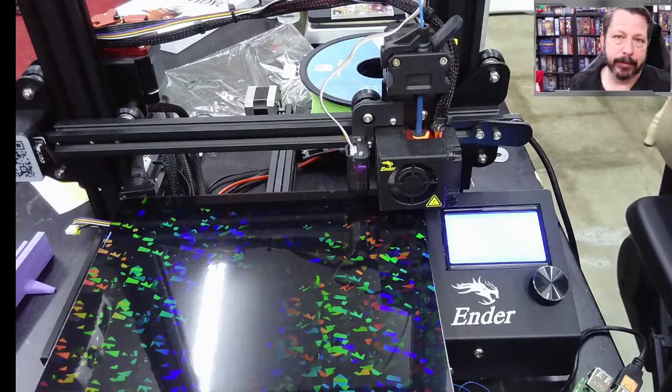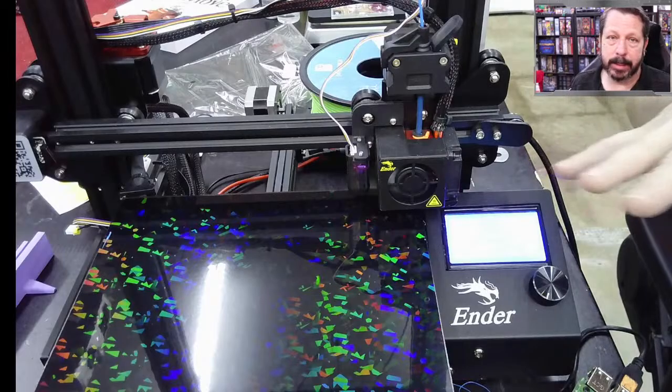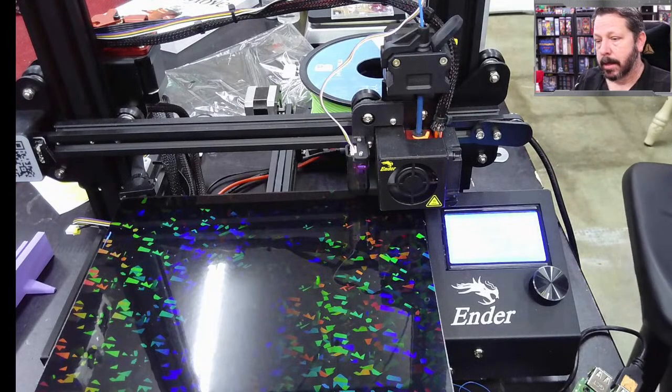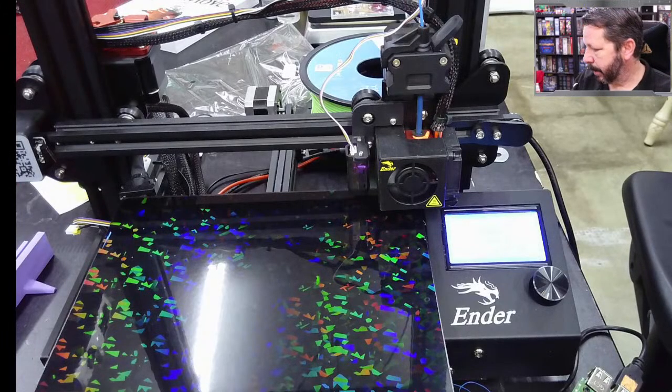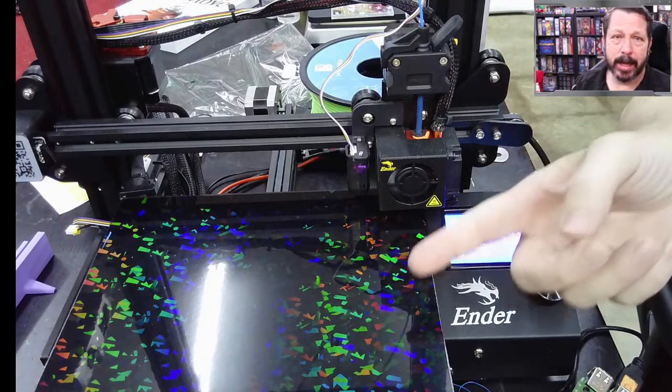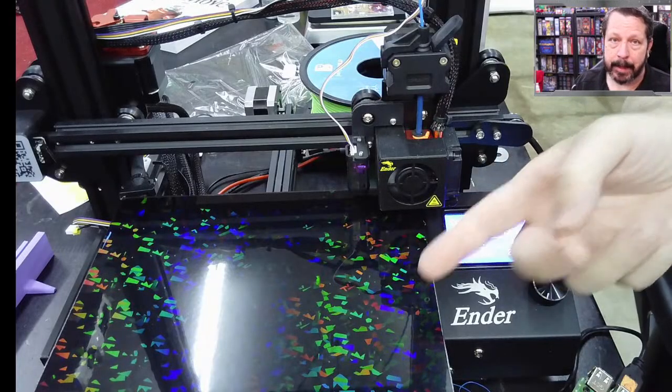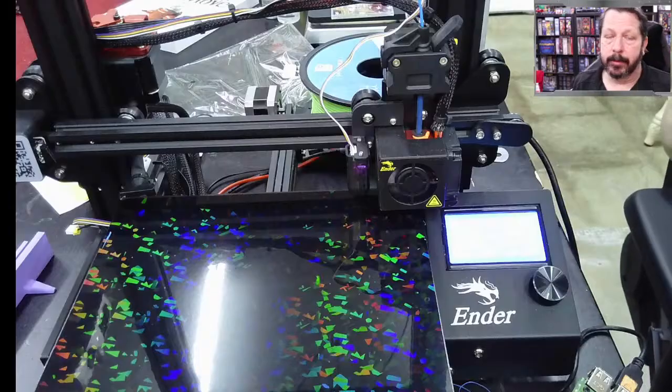Otherwise, you'll get different results. Turn it all the way on and you'll get nice parts that come apart. Turn it all the way off, you'll get very good layer adhesion, but it will kind of be lumpy. And then the bed is usually pretty hot. So I've got it set at 70. Some people print at 80 or more for the bed on PETG.